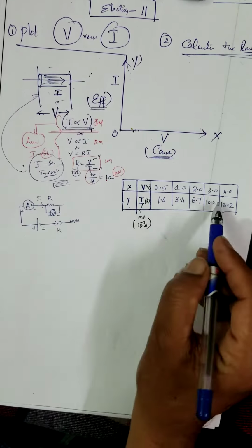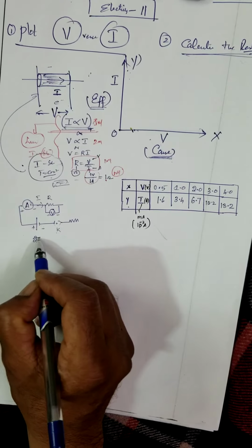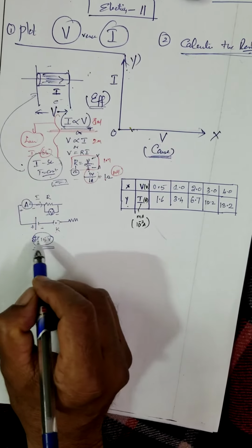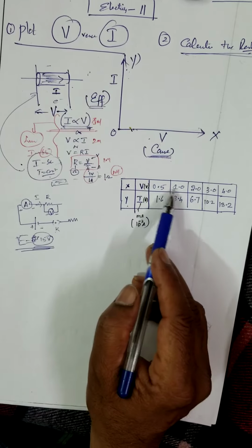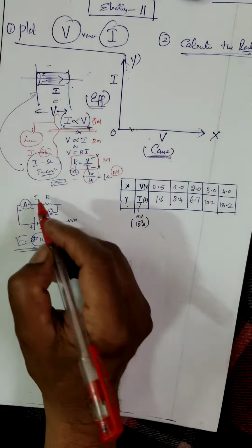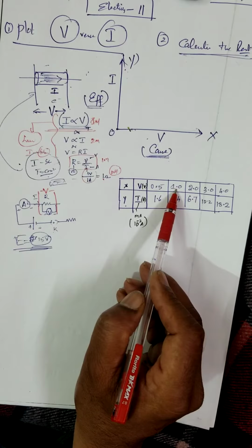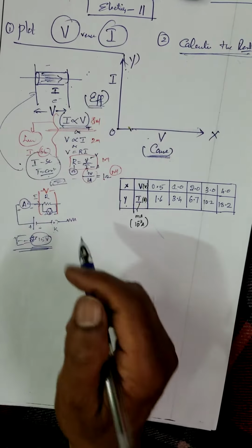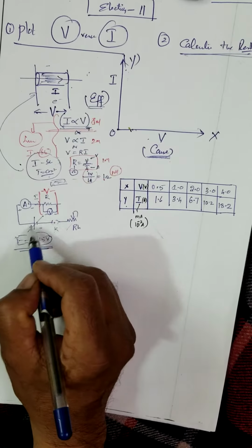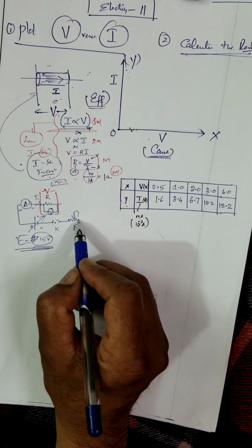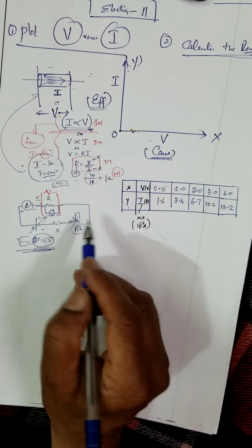And you want to vary the voltage, because suppose the power supply is maximum 15 volt, right? But you are increasing the voltage across the resistance from 0.5, 1, 2, 3, 4. For that you have one separate apparatus that is called a rheostat. The rheostat is an instrument which controls the current.